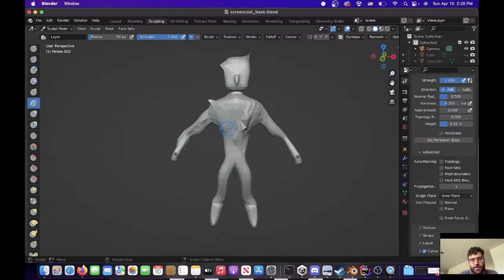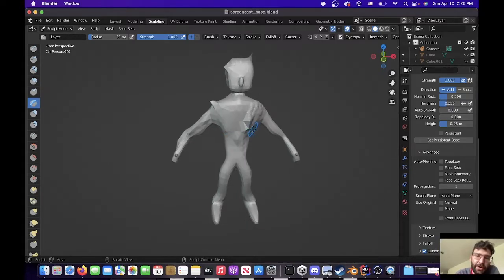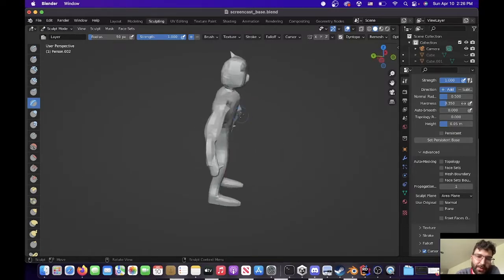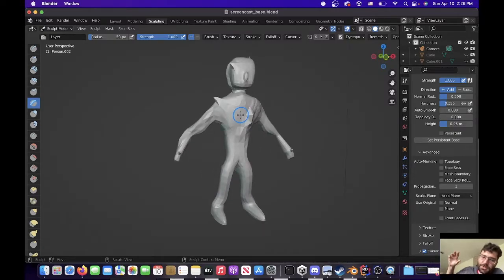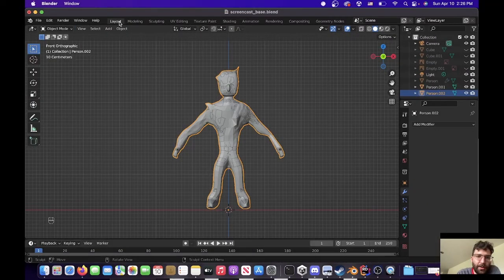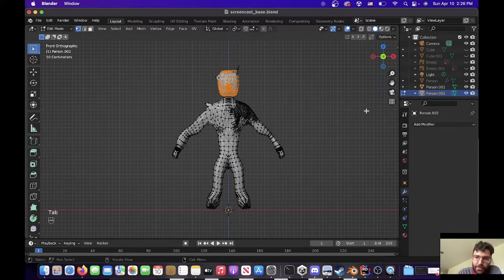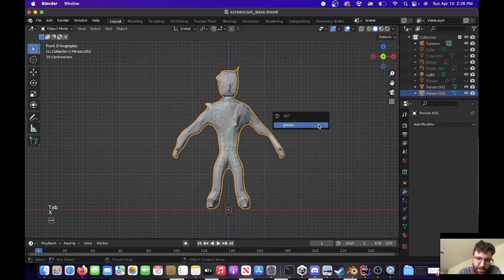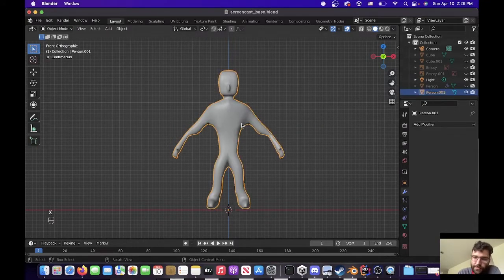If you were doing a AAA character model where you're going to have 50,000 faces and you want it to look photorealistic, ideally you would block model your low-res base mesh, then push it around in sculpt mode till it looks good, and bake the geometry details back down onto the mesh underneath. And you can see if you're not careful, dynamic topology makes many more vertices than before. So sculpting is a different workflow, which is a little too complicated for today, and one that I'm not comfortable enough with.